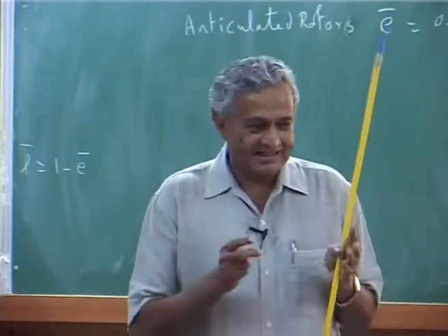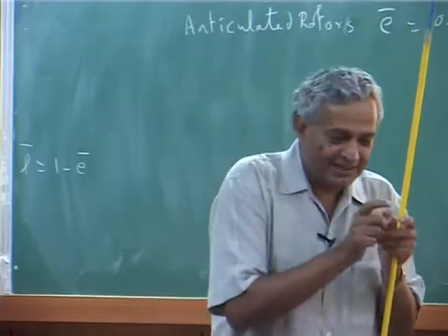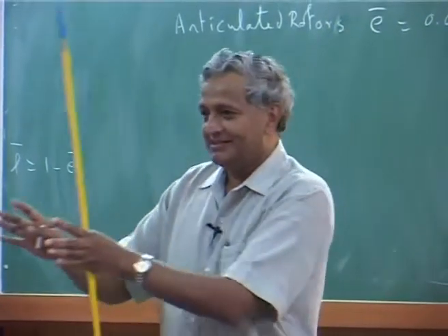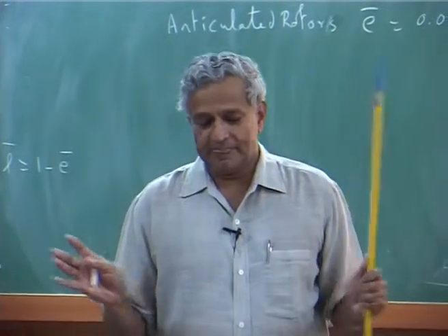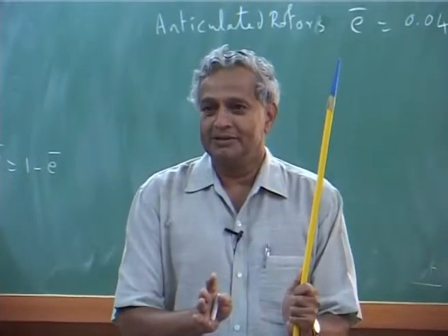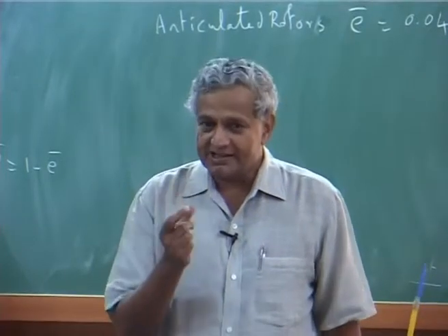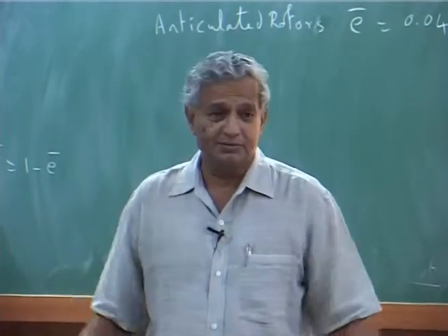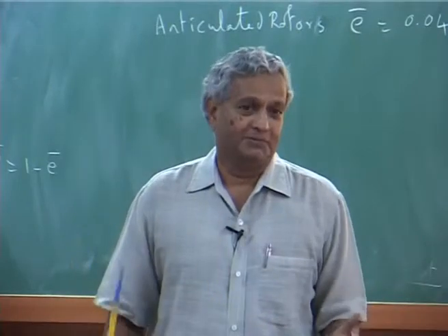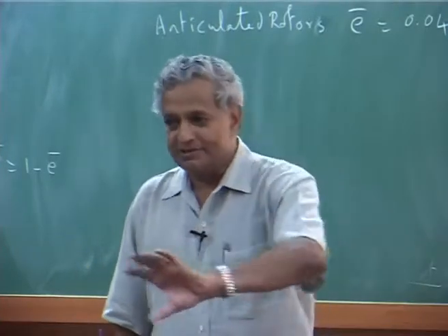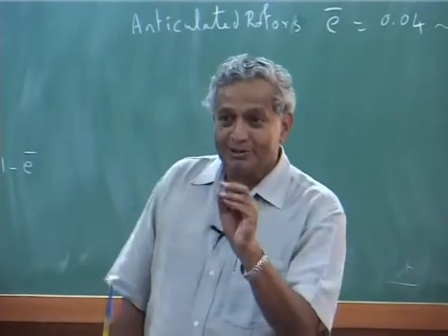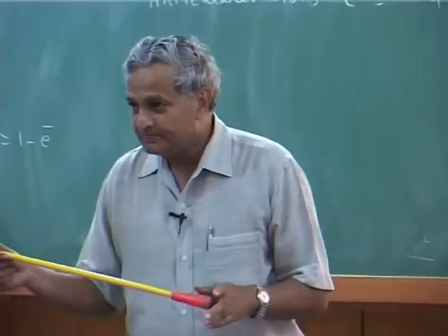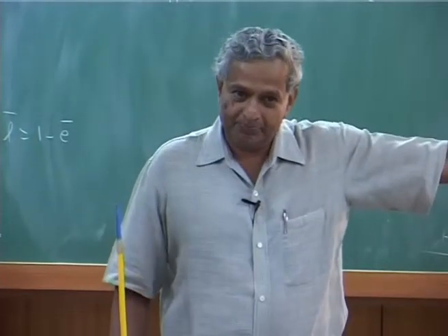So it's like, what is important for a particular dynamics, you use it. But of course, everything is part of it. But if you want to get a good understanding of the physics of the problem, do not try to put everything in and then you have no clue. So you split the problem. That is how we say, okay, lag, let me look at how the blade will move, flap alone.